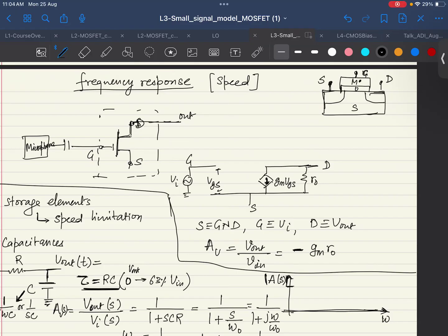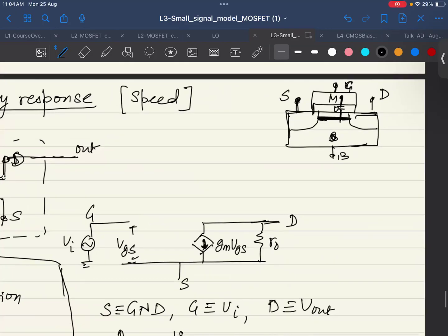Because I do know that there is a capacitance between my gate and, let's call it body so that we are not confused, channel, because I'm having a channel here. And this is all coming because of a capacitance section, right? This is what we discussed in the starting. So that means there is a capacitance at the very core of your MOSFET structure, right? Now this capacitance divides, because the source and drain are also affecting this formation of the channel.